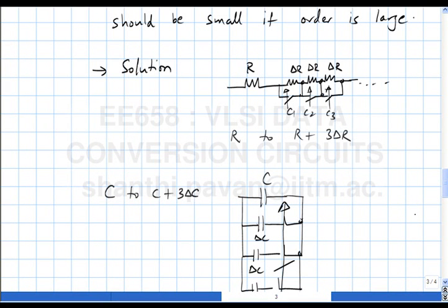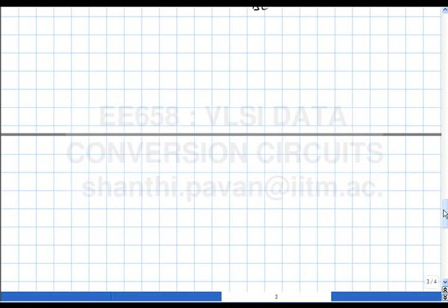There are many ways possible, where you have a system on the chip which measures the R and C. One way of doing it is, for example, to pump a fixed current I into a capacitor. Let's say this current I is of the form Vref by R, and this is C.